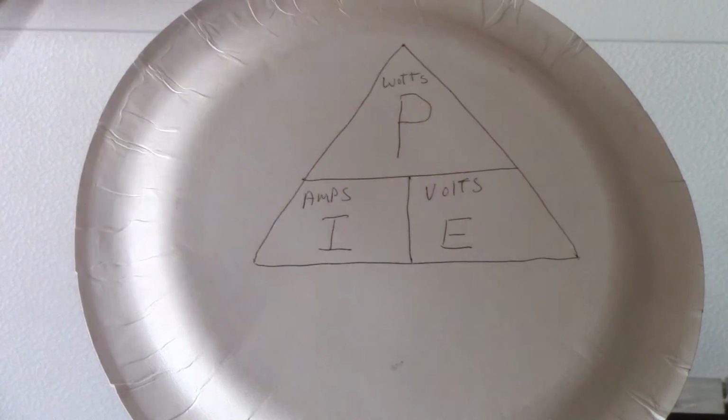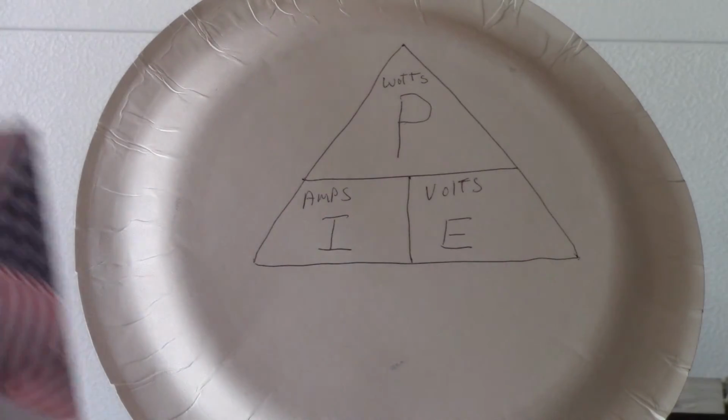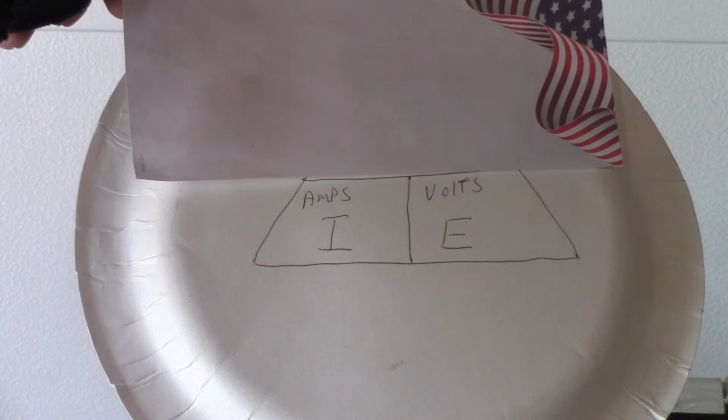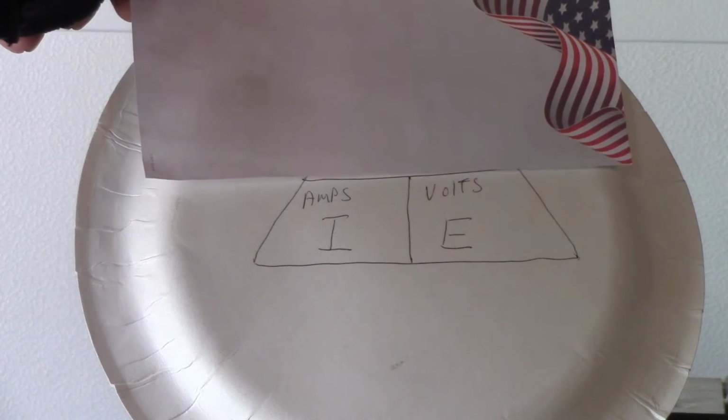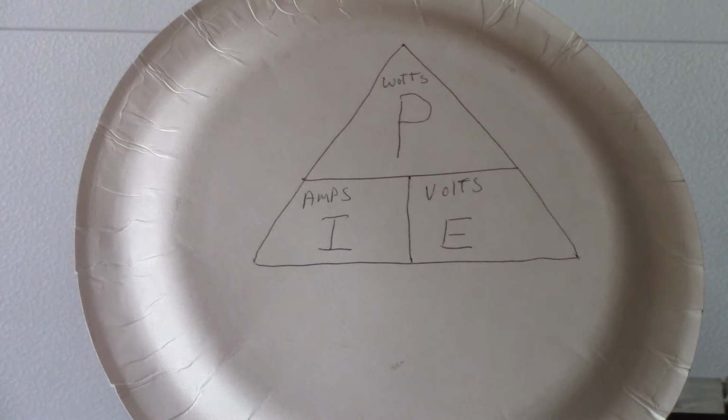3,000, that's right. Since I have two of those, if I wanted to run them in parallel and keep them at 12 volts, we would have 500 amp hours. So if I wanted to know how many watts total, what would it be? 500 times 12 is 6,000, isn't it? So now we could run a little more, maybe 1,500 watts. We could deplete those batteries overnight, right?